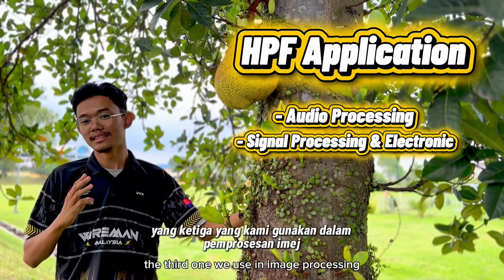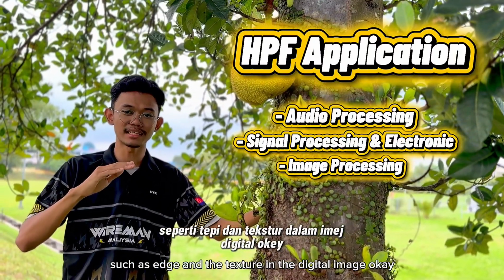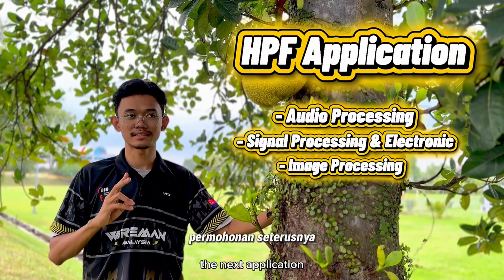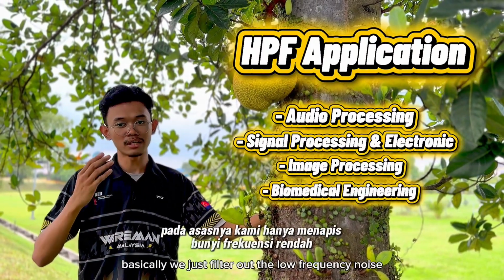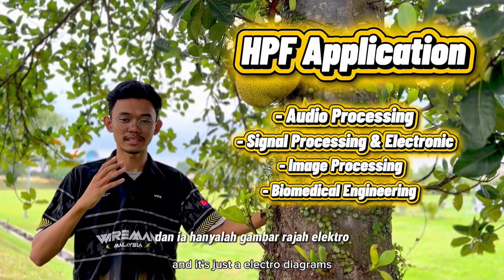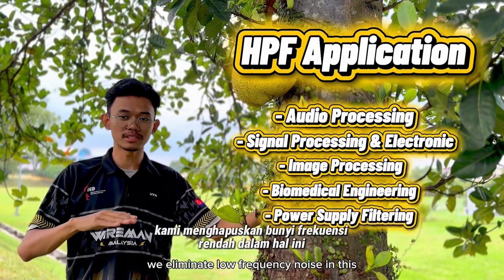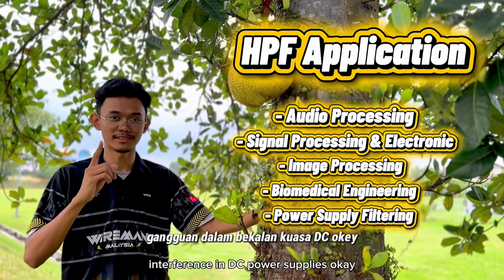The third one, we use in image processing to enhance high frequency details such as edges and textures in digital images. Okay, the next application is biomedical engineering. Basically, we filter out low frequency noise and baseline drift in signals like ECGs, electrocardiograms. And the last one is power supply. In the power supply, we eliminate low frequency noise and induced interference in DC power supplies.